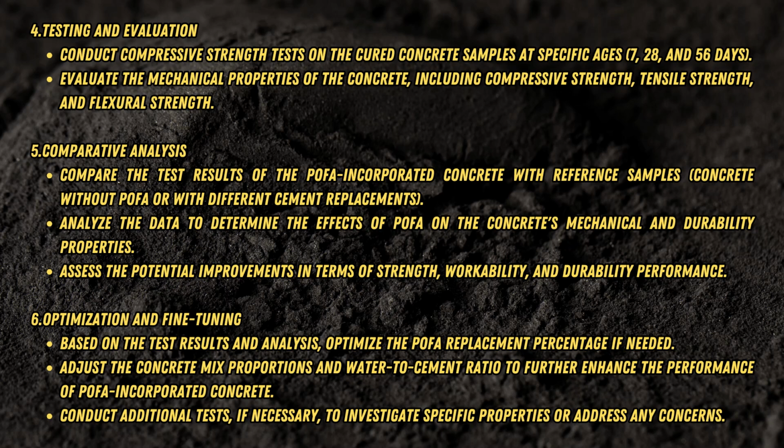And lastly, optimization and fine-tuning. Based on the test result analysis, optimize the POFA replacement percentage if needed. Adjust the concrete mix proportions and water to cement ratio to further enhance the performance of POFA incorporated concrete. Conduct additional tests if necessary to investigate specific properties or address any concerns.